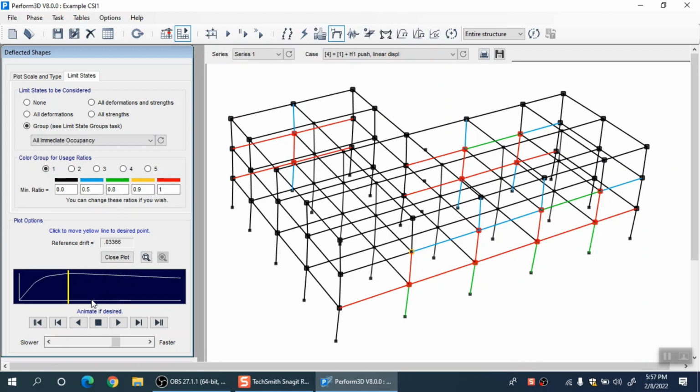So without performing nonlinear dynamic analysis, we can approximately obtain the forces and displacements which the earthquake is going to produce, right. So the first generation of performance based design was based on that idea, pushover analysis, when nonlinear dynamic analysis was not that common. So what people used to do is to estimate the peak inelastic displacement of the roof which is expected to be produced by the future earthquake. Let's say we get a number, let's say 10 centimeters for one particular building. So now all we have to do is push our building until the roof displacement becomes 10 centimeters and stop the analysis there.